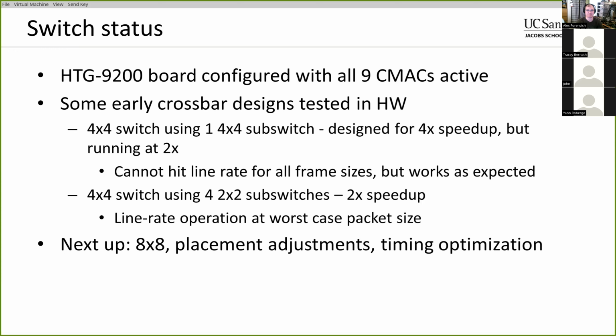So we make it work, but when we just try to, it seems like the congestion is the main problem, because if you want to store whole frames at the input and at the output, and you want to place everything in the same part of the FPGA, you're not going to meet timing. Also, we have to handle some of those reset signals that were trying to get to very far points without replication because they were inferred in Vivado as BUFG registers. So in the end we had to be solving all of this one by one.